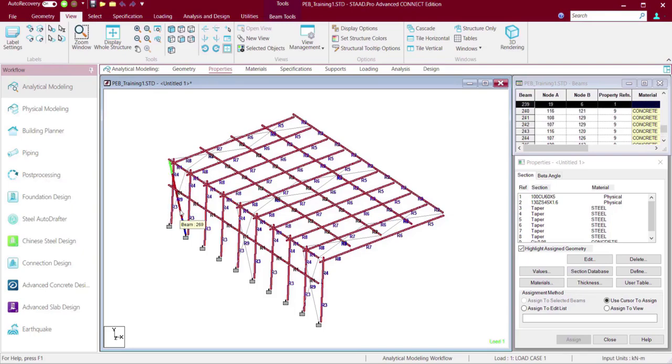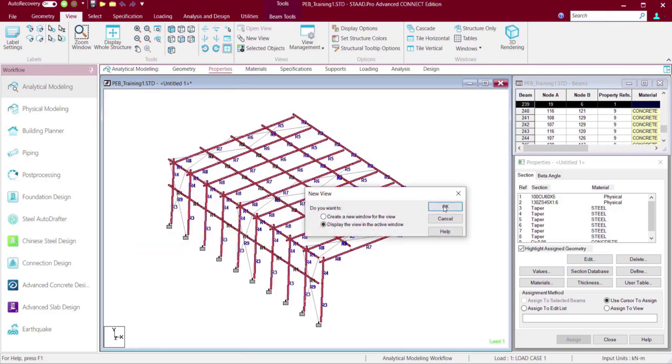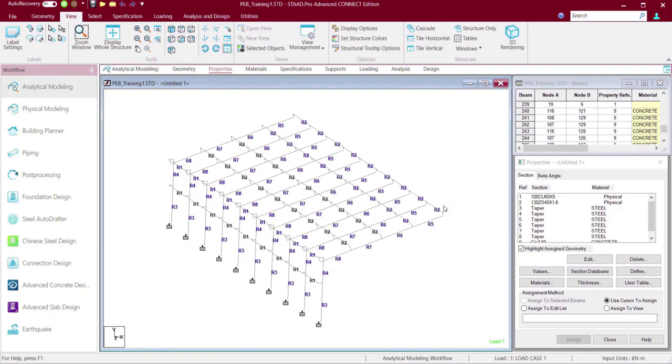So we have taken the entire slope portion as well as the vertical wall within the same group name, and we will apply the wind load with the same intensity to this entire stretch because there is no opening, so there is no point in fragmenting them. Every panel should be considered.